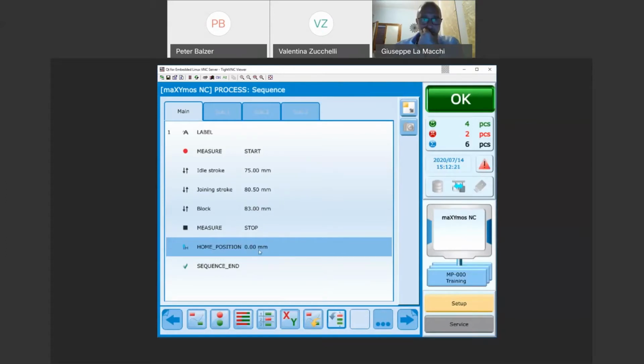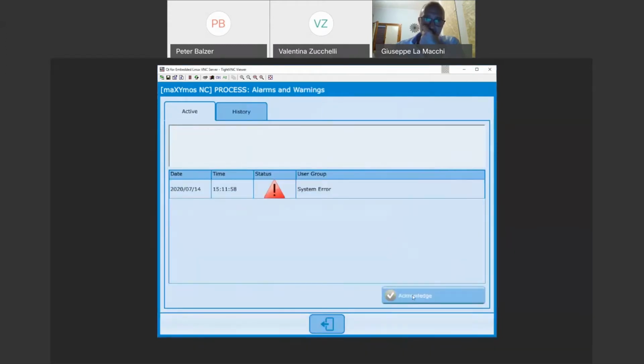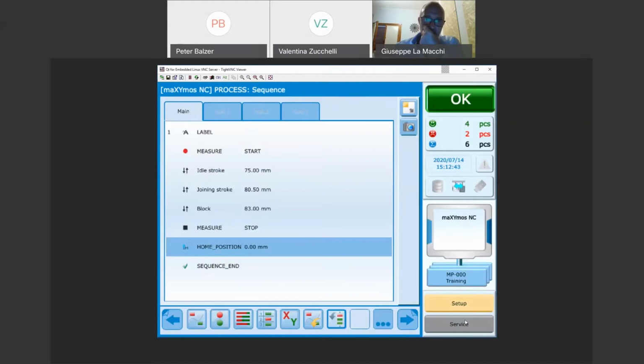So first of all we need a motion where we are able to cover more than 800 Newton and not directly go down to a limit of 100 Newton. This is not working. That's a commonly seen error on site. So now I first of all need to reset the error. Okay, then we can go back to home position.